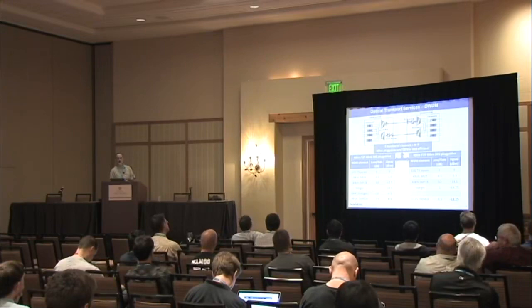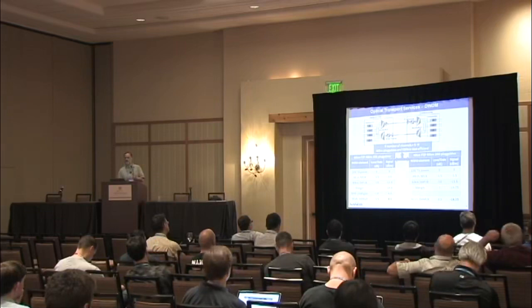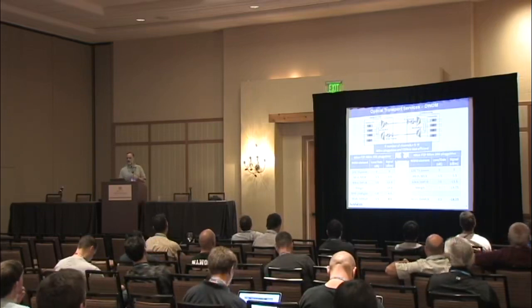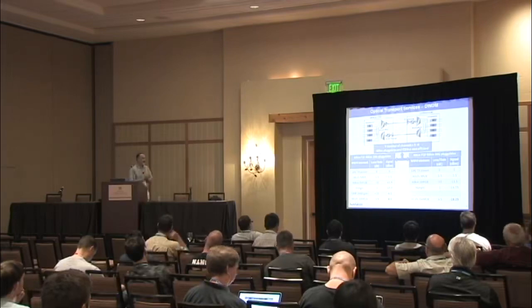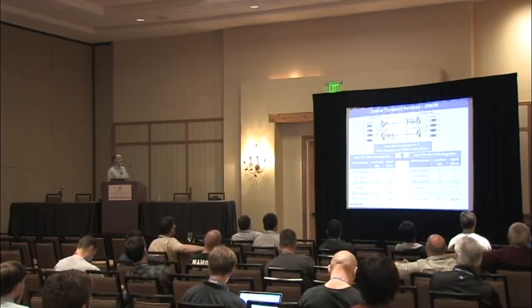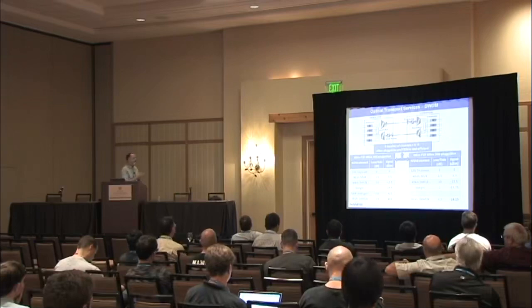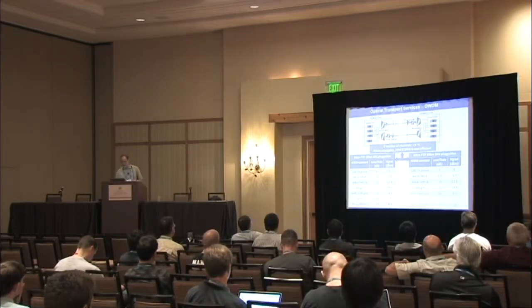Let's look at using 80 kilometer optics, with the same calculation. I don't need the amplifier. I'm getting to minus 18.25. Keep in mind, 80 kilometer optics have an effective sensitivity of minus 20, so I'm within the range of my 80 kilometer optics. The empirical cost calculation shows that if your number of channels is above 8, you are economically better off using 40 kilometer pluggables and an EDFA.